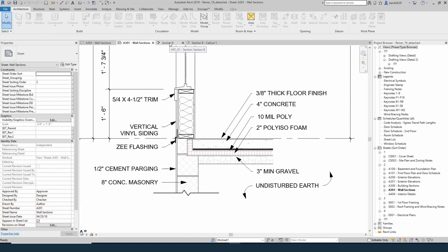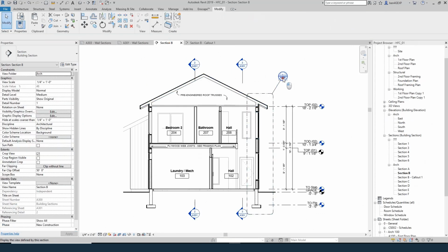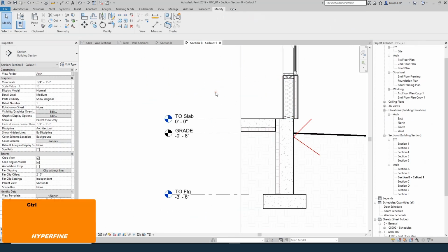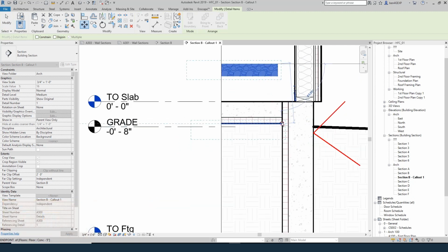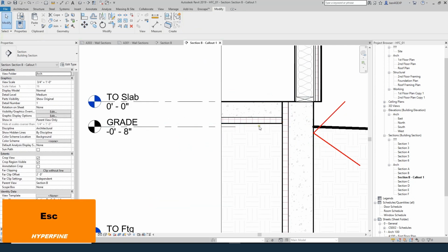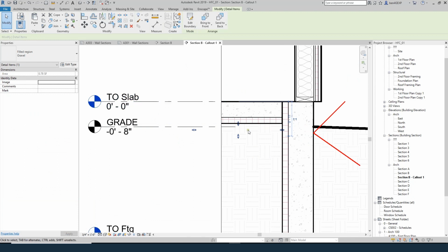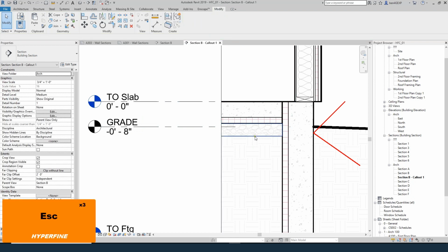And then you can check that other video about the 5 ways that I covered for copying stuff over. So if I just paste this into place, and luckily this is already sort of the shape and size that I need, I'll set that one up. I'll just bring that right there. You can have a front and back sort of. Revit is not built in layers, but these filled regions do work in layers. So if I bring this to the front, there now it's showing up over.